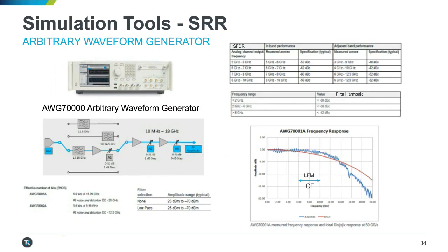For short-range radar, we need better range resolution because the targets are potentially going to be less than a meter away. So we need very large chirps, 4 gigahertz, 3 gigahertz, maybe even 6 as we go forward.